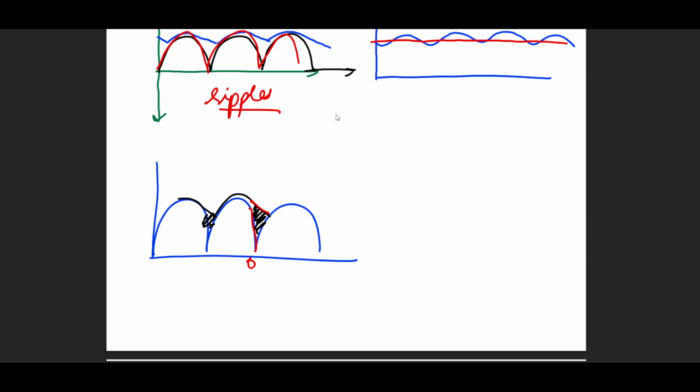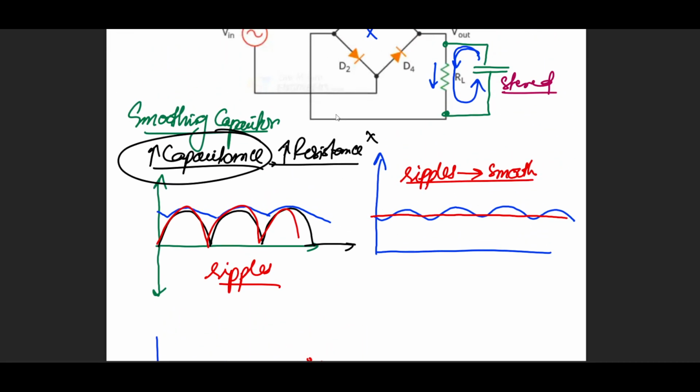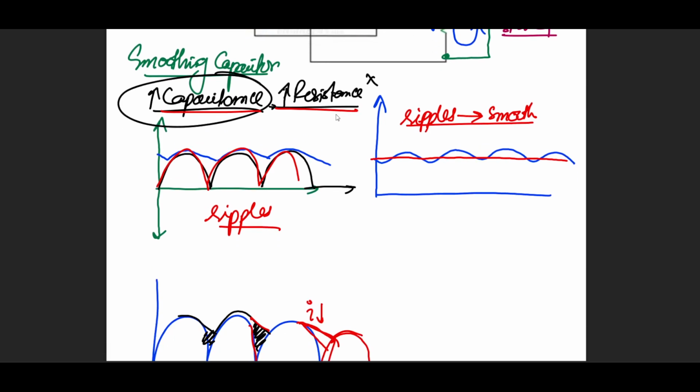So if you increase the resistance, what actually happens is that this fall of current is delayed. Previously, the current would fall like this, because the resistance is low, the current is high, and energy will be taken from the capacitor very quickly. But if you increase the resistance, the current is restricted and the fall is slowed down. So the voltage graph falls less, and the AC supply has more time to come back up to the maximum value, take charge from the capacitor back and then supply energy to the resistor. So increasing resistance and capacitance both have an increased smoothing effect.